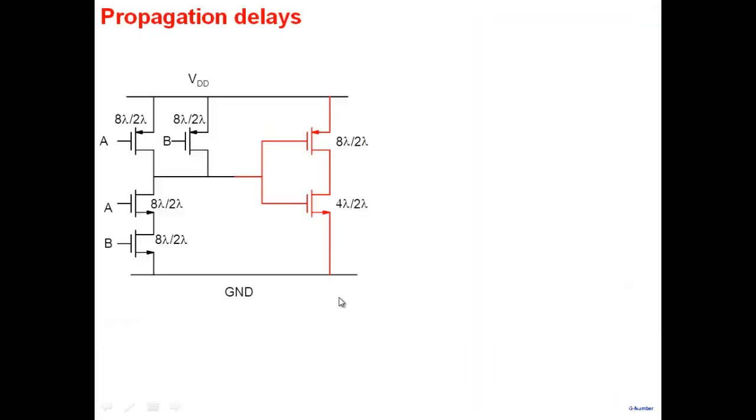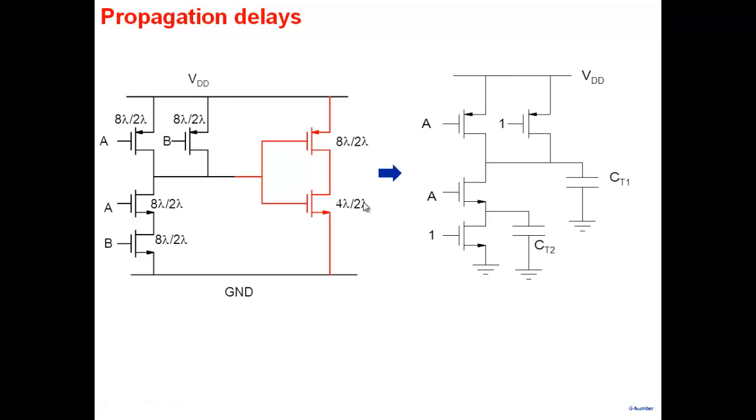So this is our NAND gate, and what we are doing is we are taking an inverter as a load for a NAND gate. And so what we'll do is we'll examine the delay under this condition. Let's say this is permanently connected to 1 first, and this is the node which is switching. If we try to lump all the capacitances, I end up getting two important nodes. One is this particular node, where we lump up capacitances here, and one is an internal node, where we need to lump up capacitances here.